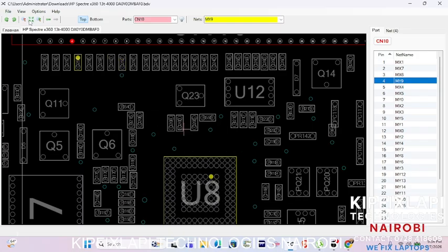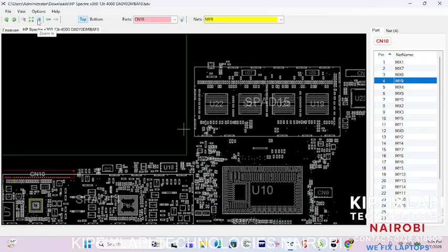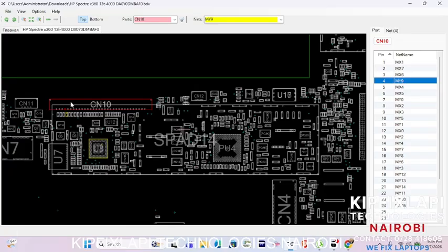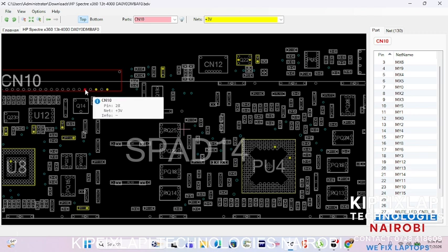Now, with some other board viewer software, when you click a pin, let's say we click this pin, it will show direct lines all the way from this pin. This is pin number 28. You can see that pin number 28 has nets with +3 voltage. You can see now this Boardview file can also show you the measurements, which pin should have what.